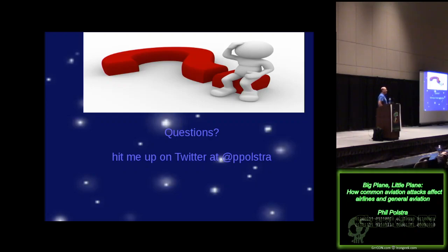Yeah. And if you're talking about an airliner, an airliner is going to have some sophisticated stuff. If you're close to the ground, they usually have what we call radar altimeters, which literally reflect radar signals off the ground. So when you're low, you would know that. And that's going to be tied into the TCAS system, and you're going to get alerts telling you, pull up, you're low. So hopefully you would notice it.